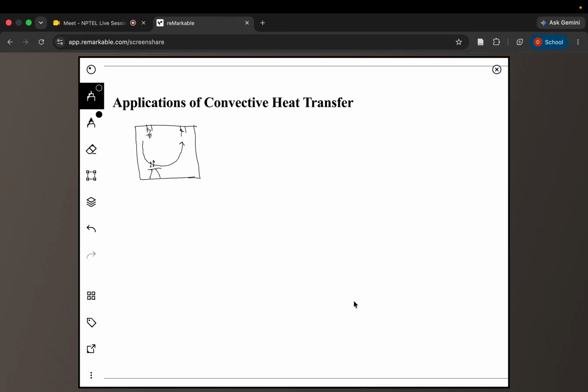The question we need to answer is, depending on your metabolic rate and your activity state, you are going to release a certain amount of heat. How much of that heat can actually be taken by the air that is being circulated inside the room? If you emit around 100 watts of heat and the air capacity is only 50 watts of heat that it can take because of whatever configuration you have, then that would result in a net increase in the temperature of the room.